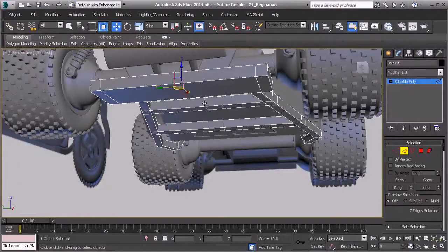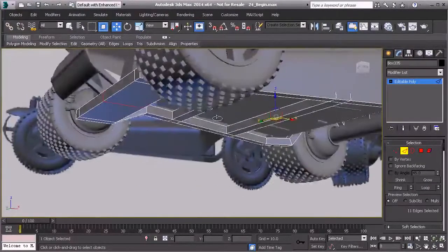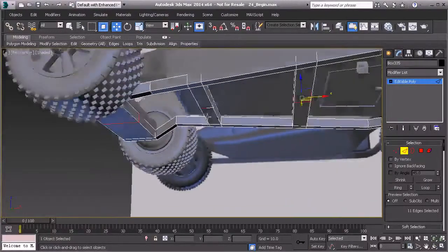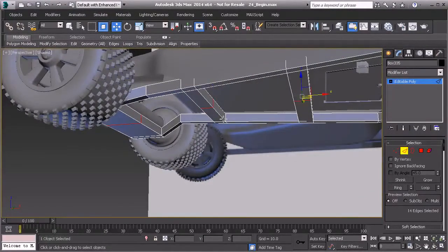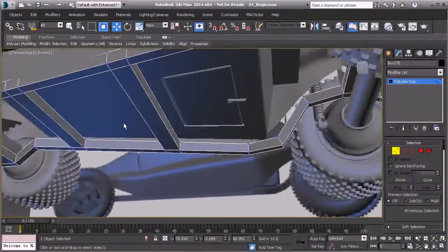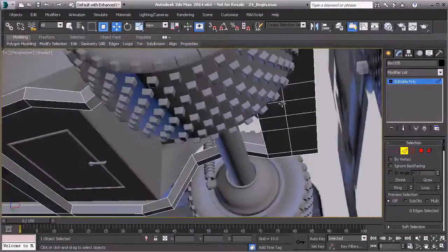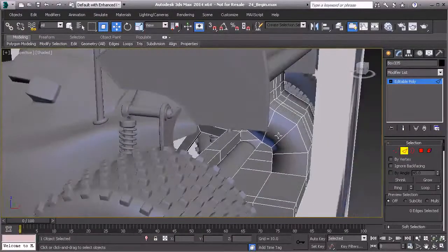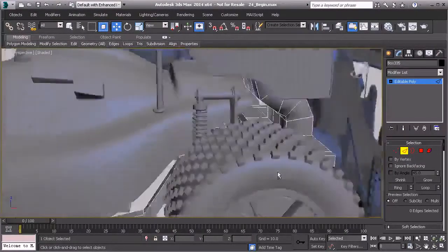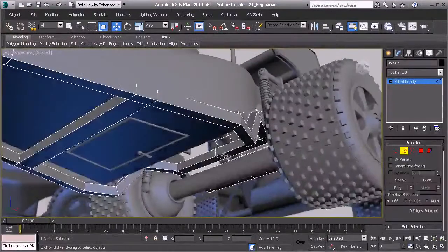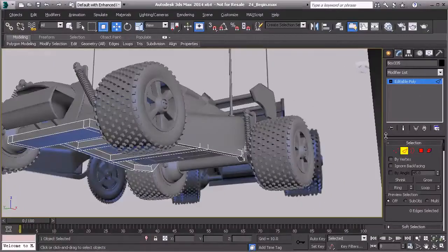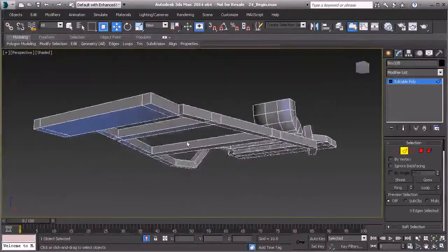And I'm going to double click on all of those parts, all those center segments. And I'm going to hit Control Backspace on those to remove their vertices and their edges. So go to Edge Mode and just remove that along the center on all of those. Okay, this one's good. And we have one more right here. It's not absolutely needed. And we could also apply Turbo Smooth to this.